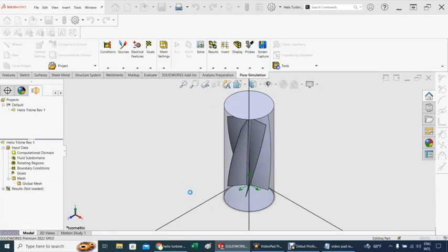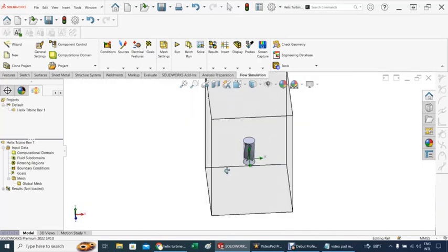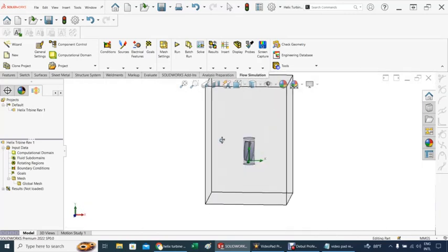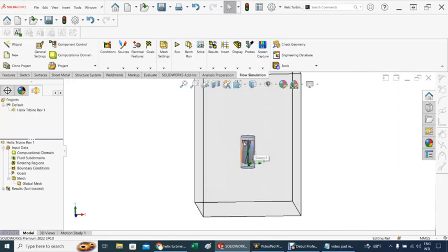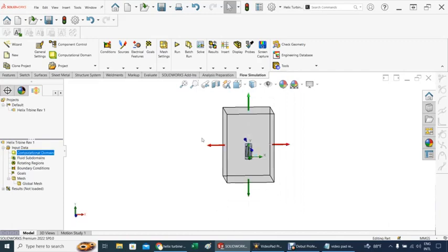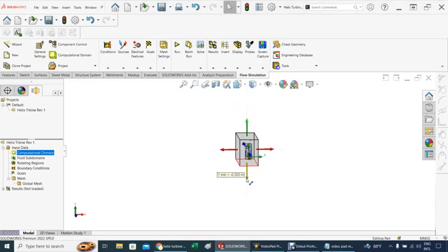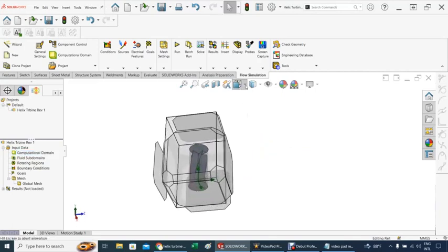There we go. Now, still doing some work there. Now let me get this. You see, I would say the computational domain is huge because I only really care about things close to the spinner in this case. So let me get this smaller so that the computational time or effort that the computer takes to do this is not a big deal, because otherwise if I leave that box that big, it's gonna take forever on this computer. Maybe on a supercomputer that will be a few minutes, but in this one, guarantee it's gonna take a while.